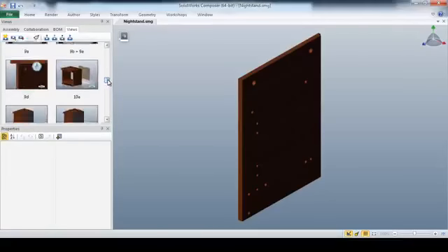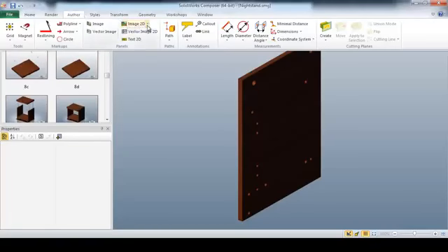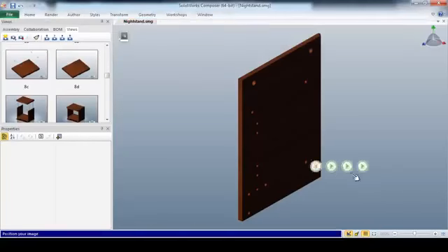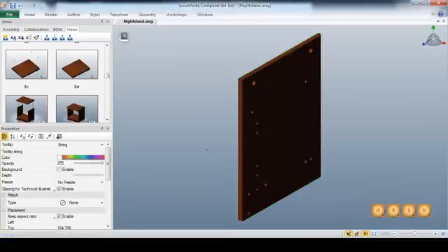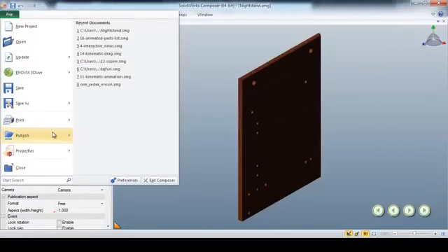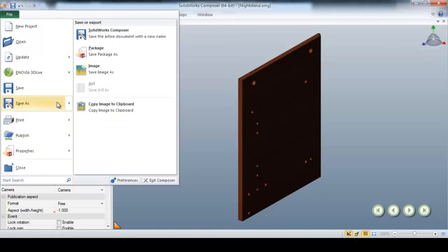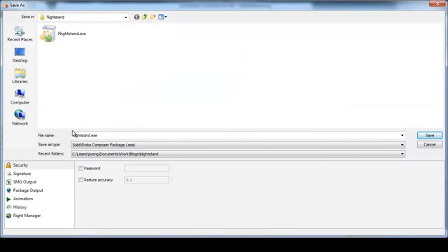After repeating this process for the remaining assembly steps, I can quickly drag and drop pre-programmed widgets which will allow the end user to quickly navigate our digital instructions. With our widgets now in place, publishing our instructions is just a matter of a few clicks. I'll simply go to File, Publish, and then I can choose from a variety of file outputs like HTML, PDF, publish online, or publish to an email. For our interactive instructions, however, I'm going to choose the package feature, which will create a fully interactive .exe file.